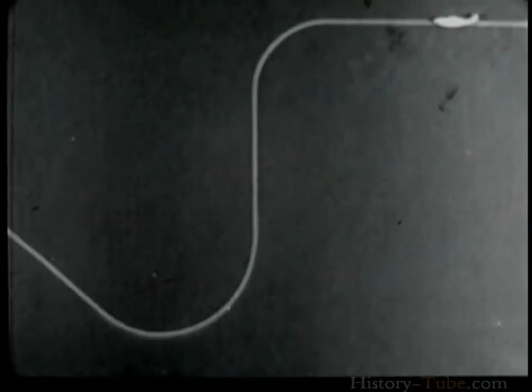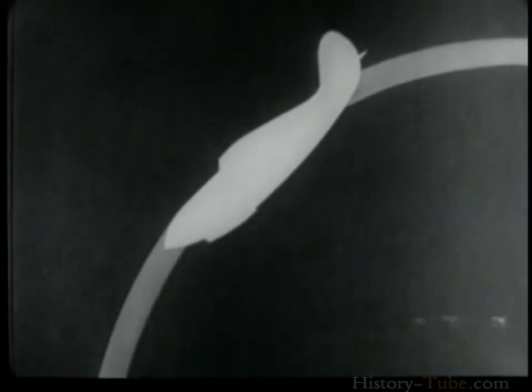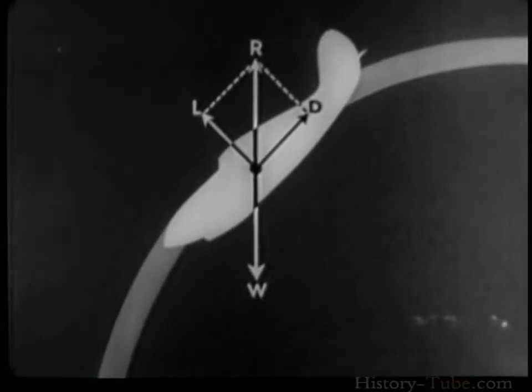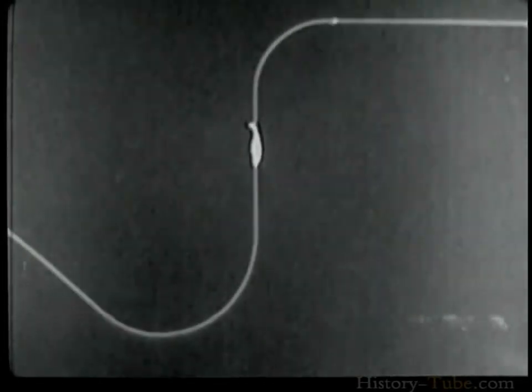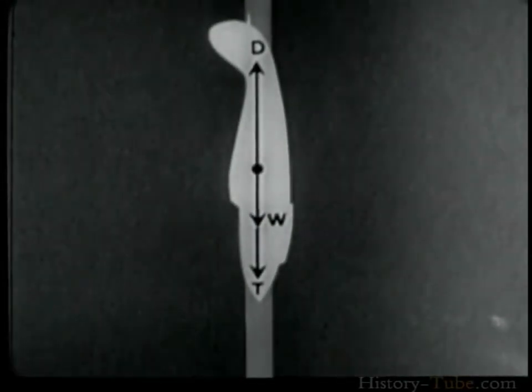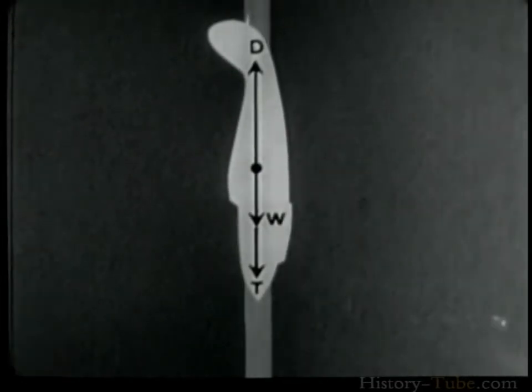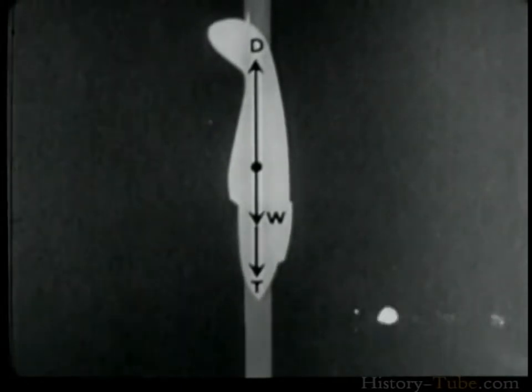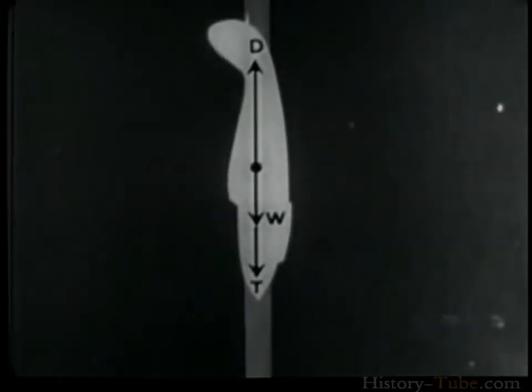Consider the case of an airplane flying horizontally at a small positive angle of attack. As the controls are set to put the airplane into a dive, the angle of attack decreases and the speed increases. Lift decreases, since in this attitude the weight of the airplane is opposed by the resultant of lift and drag. As the flight approaches the vertical, speed increases until the terminal velocity is reached in the so-called vertical dive. In this condition, lift is 0, and the weight of the airplane plus its thrust are opposed by drag alone.